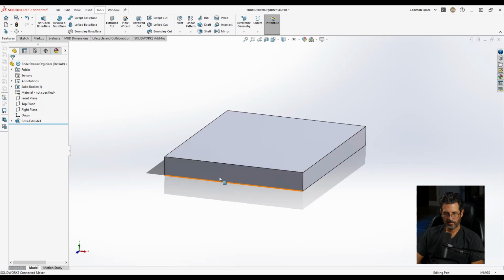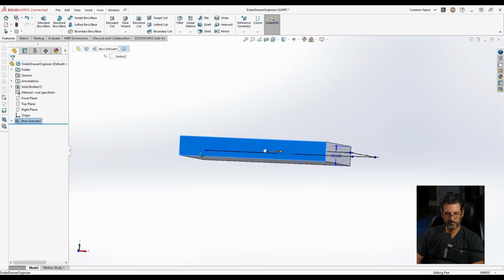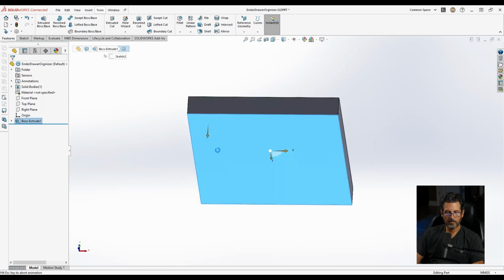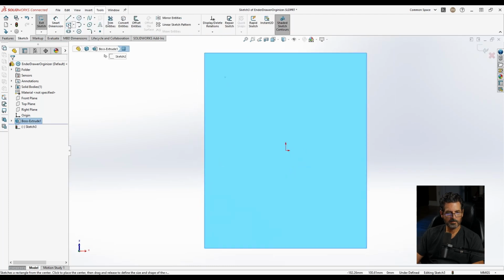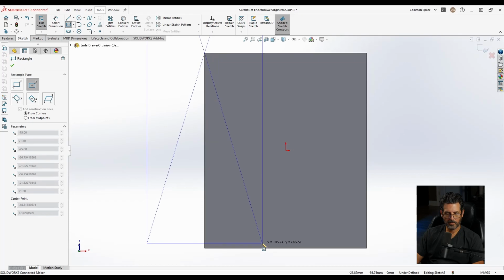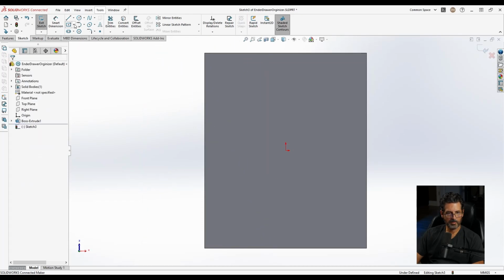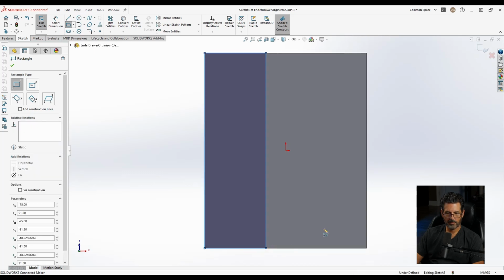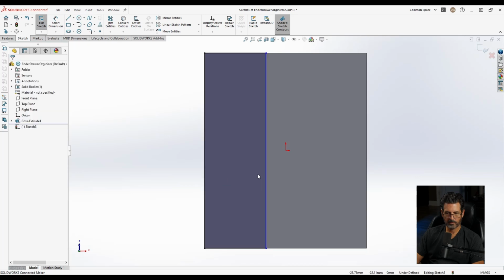Now there's a couple things that have to happen here. There is a step on one side. Let's see what side I want that on. Okay, so to step that up, I'll step it up on this side. So let's create a sketch there. Going to draw a rectangle, not about the center, but a corner rectangle, and go from that corner down to this line here, because it's going to go all the way across.